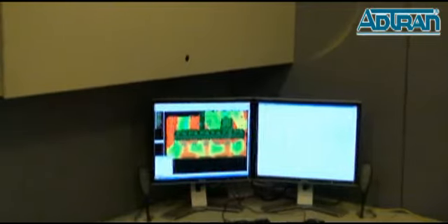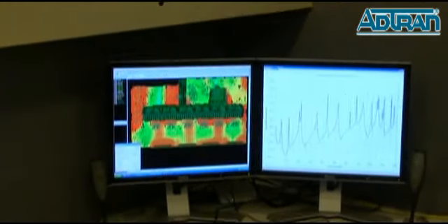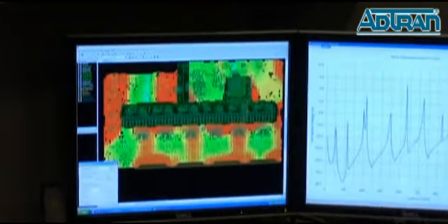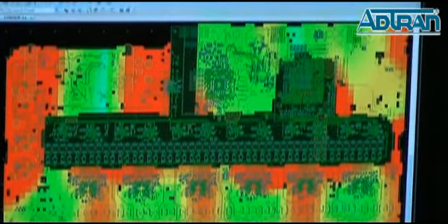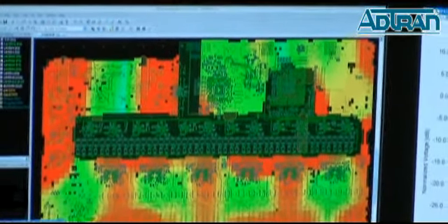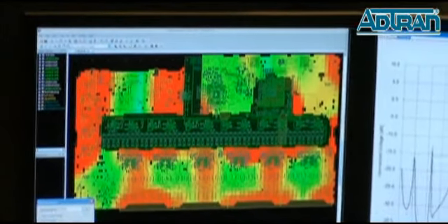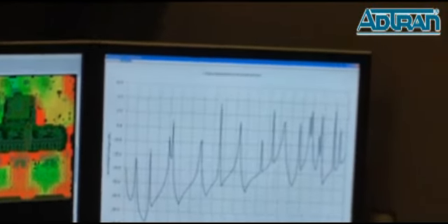Okay, thanks. So tell us about this tool on the screen. Okay, we mentioned earlier, if there is a failure, what do we do? One of the tools we have is a computer simulation software. We actually import the information about this printed circuit board. We do simulations on it to identify hotspots, which you would see in red, and that gives us a chance to simulate what we're seeing, try some fixes in simulations before we actually put it into the actual printed circuit board and make sure that it would comply after the fact.